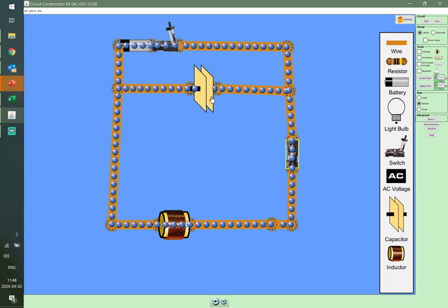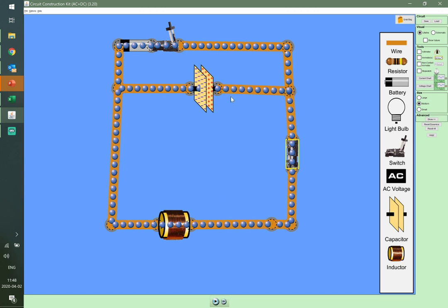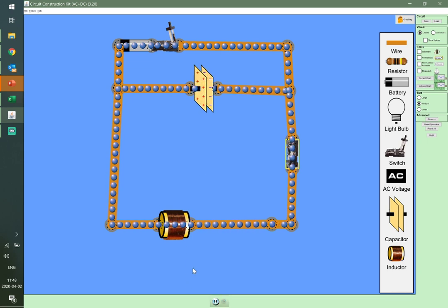But now that the capacitor is discharged, you might think that things would stop, but they won't, because there's still current going through this inductor. And the inductor will try to maintain that same current in the same direction. So what's going to happen is it's going to keep pushing charges until it builds up negative charges on this plate over here. Until the inductor is out of energy and you're quote-unquote fully charged again, then the capacitor will start pushing things back the other way. And then it'll overshoot because of the inductor being there, back and forth, back and forth.